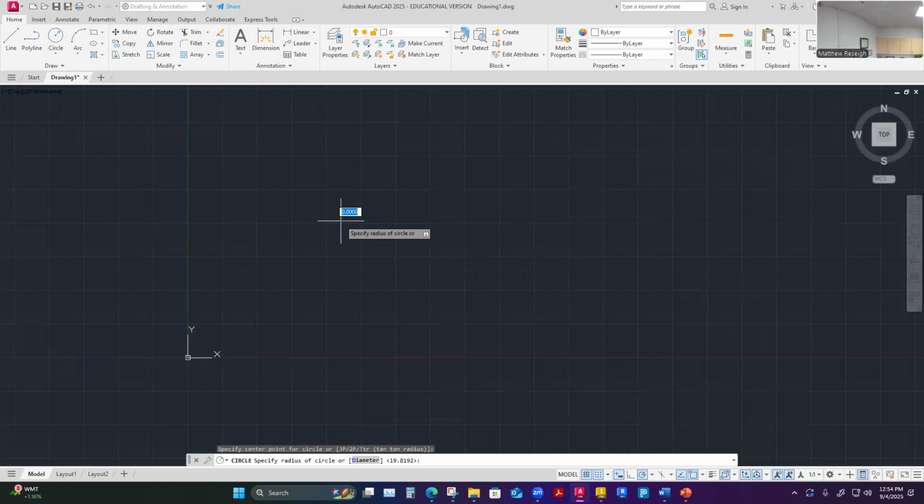It really wants you to draw a circle by its radius, which is from the center out, given as a dimension. I can input a dimension. Once I've clicked the center of the circle, what is active on my screen is the dynamic input, where I can use the number pad to type in a number.